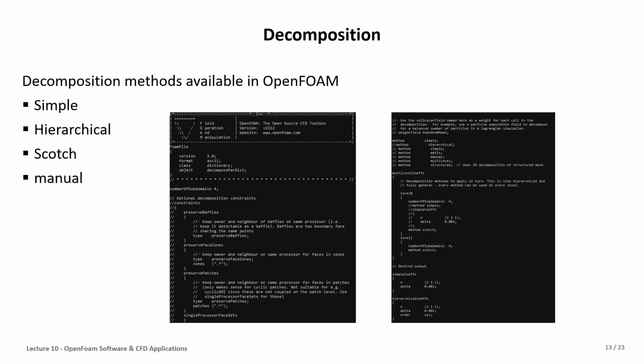decomposition setup on the domain, and the selection of these different methods requires knowledge about this structure, how it makes the decomposition, because based on the geometry, sometimes we have symmetric geometry, sometimes not, and sometimes the geometry has a bad shape, or on the meshing, sometimes we are dealing with structured or unstructured meshes. Then it's required to select the best one to have an efficient solution in the HPC and also a proper result.